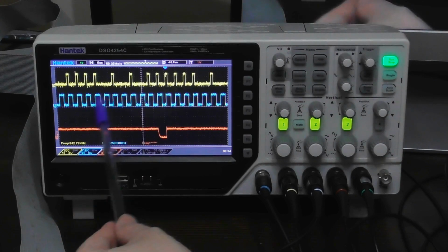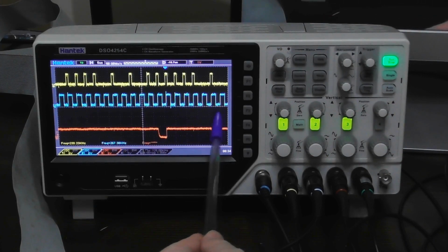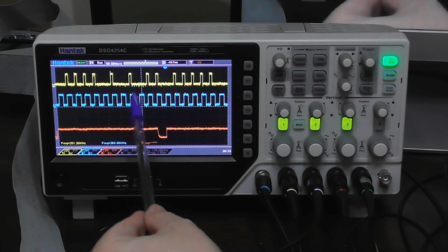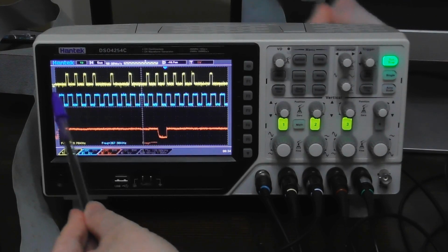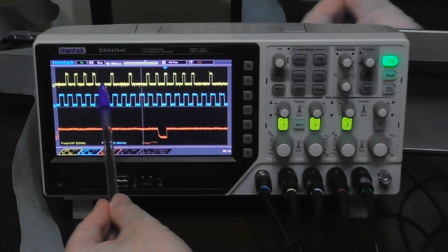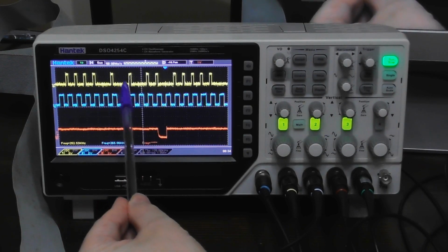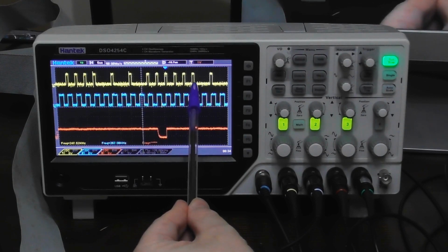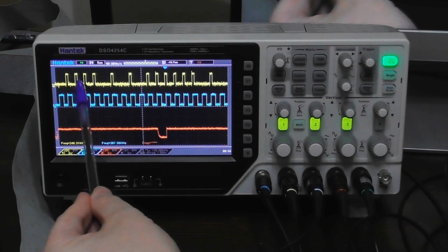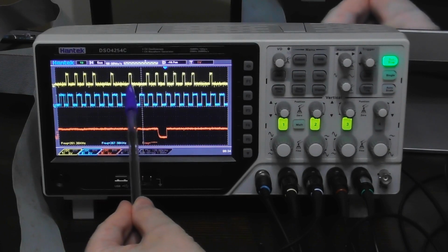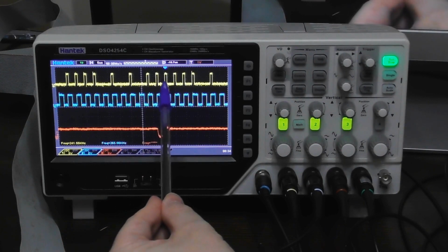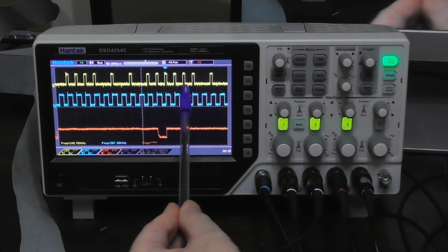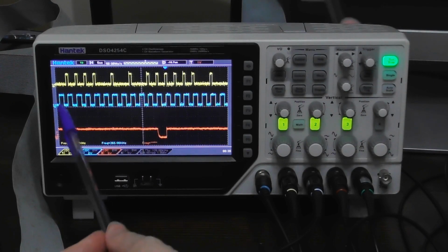Anyway, you can see at the top now, this is the reconstructed clock signal, this is the data signal from the drive, inverted, so up means 1 now and down means 0, and you can see the standard pattern of 1 1 0 0 for C in the clock, and then 0 1 1 1 is 7, so that's C7 in the clock line, and in the data line we've got 1 1 1 1, then we have 1, and either 1 1 0 or 0 1 1, you'll see from time to time,